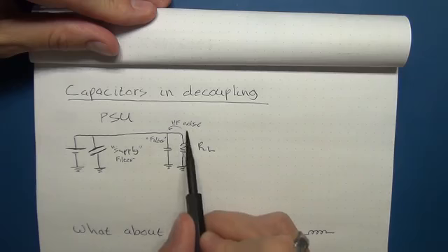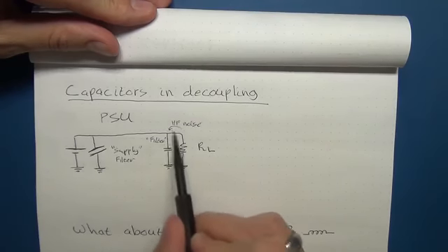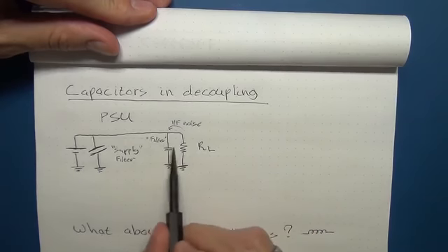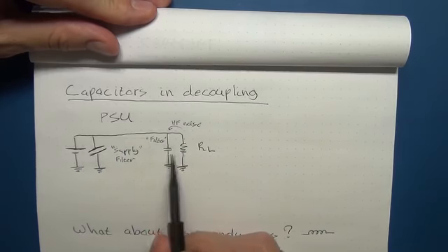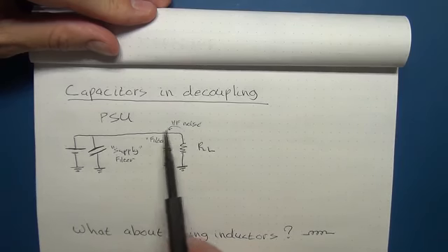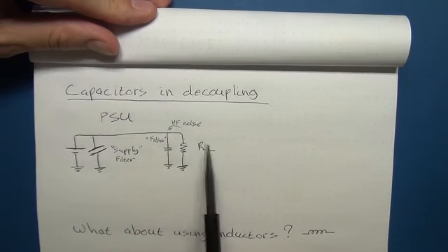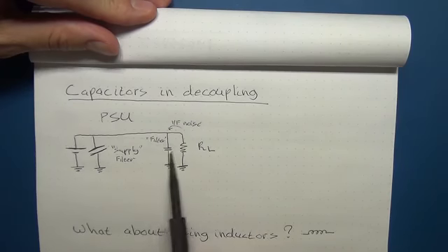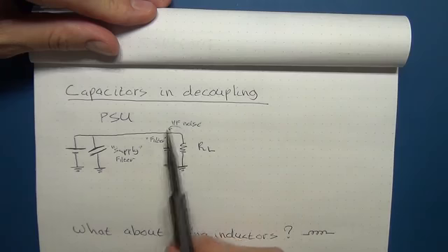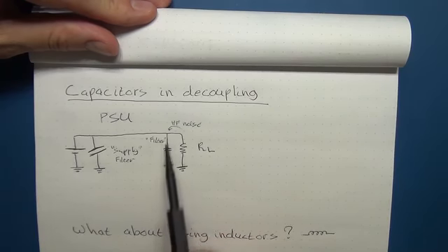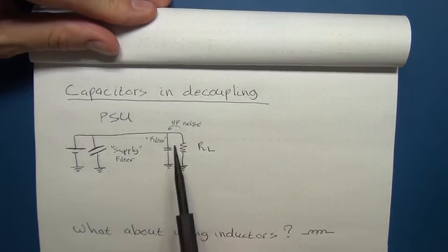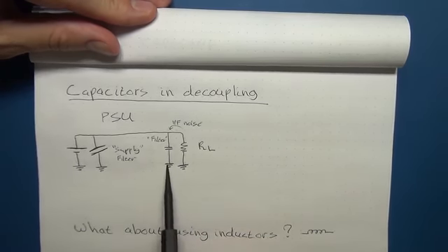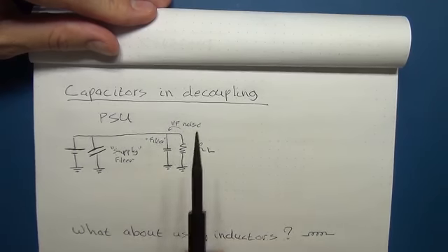Now in this situation over here, where you could have some high frequency noise, i.e. some AC going up and down over here, which you want to remove, if you put a smaller value capacitor, and of course when I say smaller value, there are calculations to understand, depending on the resistance values and the frequency that you're dealing with, to work out the capacitance value. But here, as you can understand, if you've got that high frequency AC going back and forth, that will be passed through the capacitor and taken down to ground and removed for the most part.